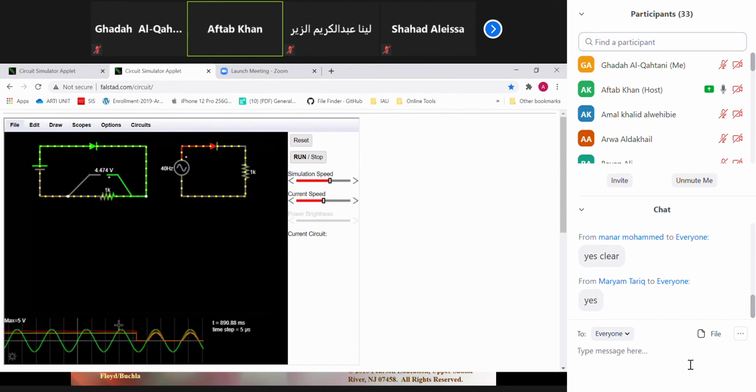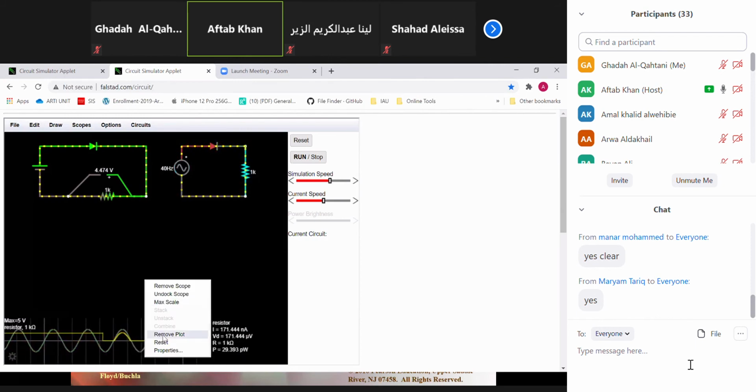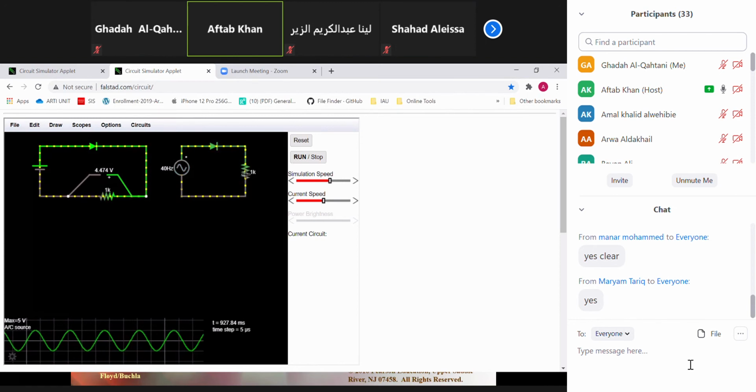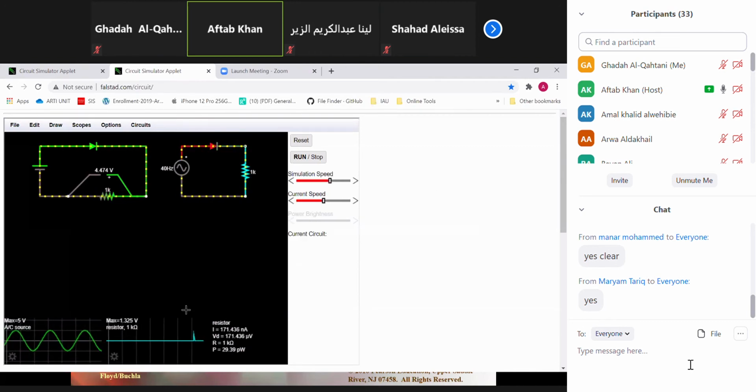So I will do one thing, just remove this plot first so that you can see all the plots separately. Okay, so this is the input. Now this is the output which we are getting across this one. In the new scope, this is the input and this is the output. So it is clear now. It is just filtering only the positive cycle. The yellow one here is the current actually, and the other is the voltage across the resistance.